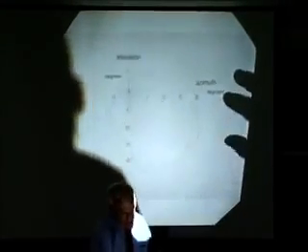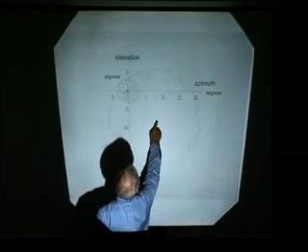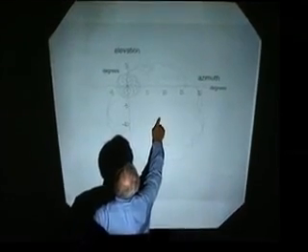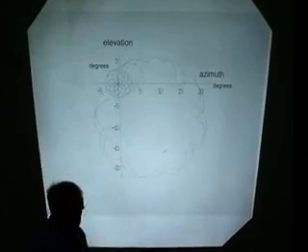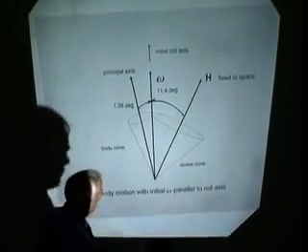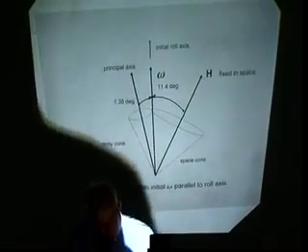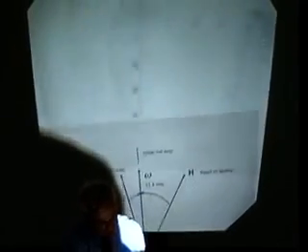This is the exact numerical integration, and you see that the angular momentum vector is somewhere in here. The theory for equal inertias, if you sort of average those two inertias and use that, says that cone would have been 11.4 degrees away. So this elegant solution very well predicts what the actual equations would say.